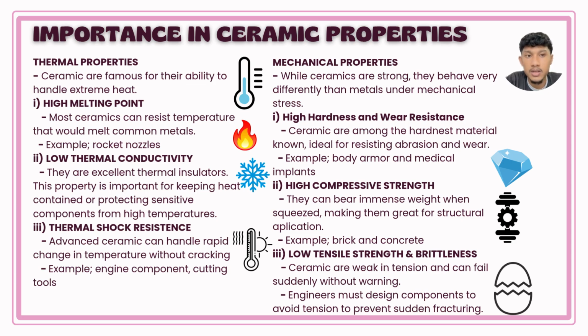Next is mechanical properties. Ceramics are very hard and wear resistant, so they are used in cutting tools and medical implants. They also have high compressive strength, which means they can support heavy weight, like in brick and concrete. But ceramics are brittle, so they can break easily under tension or impact. This is their main weakness.